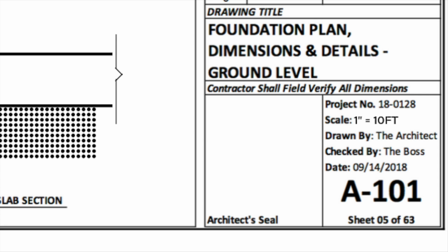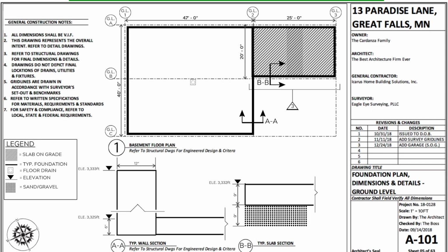And it's worth noting that when it comes to scaling, the drawing must be printed in its intended size, meaning to say that if the scale applies to a drawing that's 24 by 36 inches, it will be thrown out of whack if you printed it on an 8.5 by 11 sheet of paper, which would of course render the scale useless. So now that the written portion of this drawing on the right-hand side of the column is understood, let's review reading the actual drawing itself.